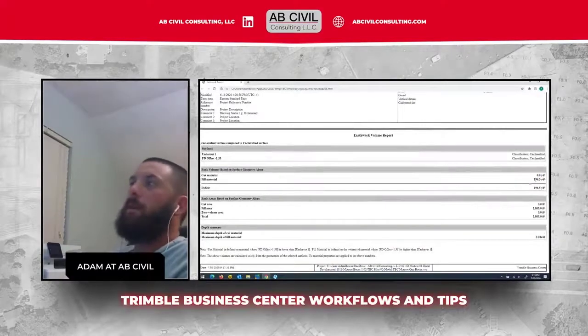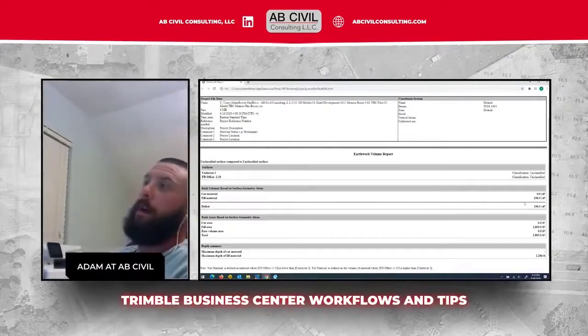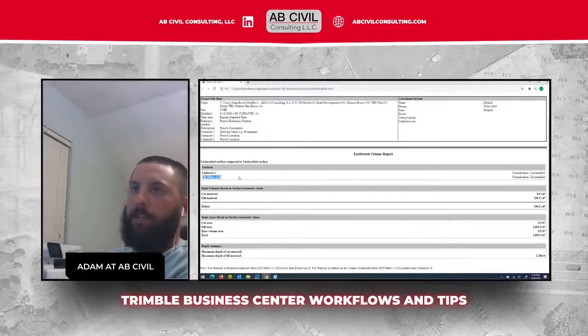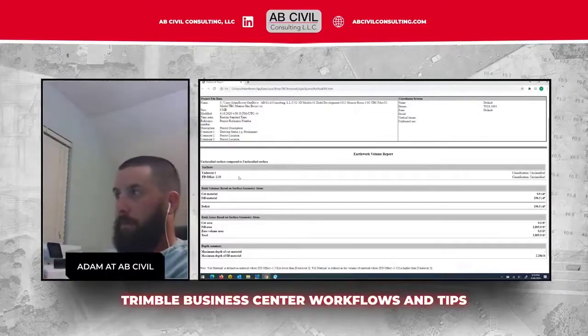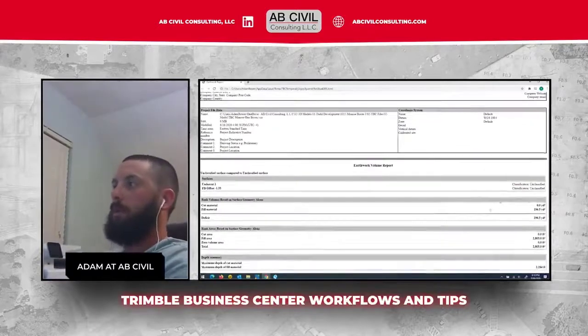So fill material. Of course this is fill to the grade we're looking for, which is an offset of finished grade. So 197 yards to finished grade. That is actually the material that they cut out. That's why I said it sounds kind of backwards. But this is just the way I normally do things. So we took a topo. It was supposed to be at finished design minus 1.33. It is a fill of 197 yards to get to that point, which means the owner of this job owes them that cost, whatever their unit price is, times this quantity for that undercut.